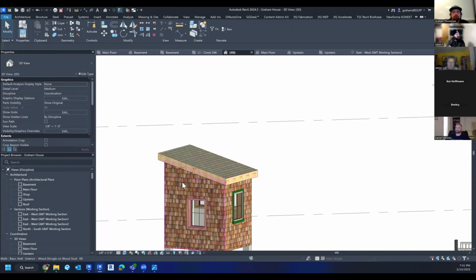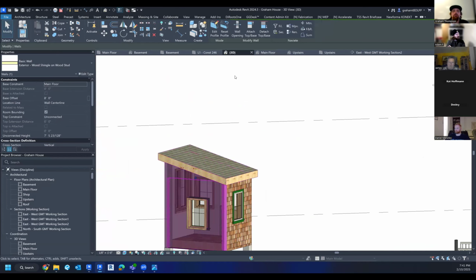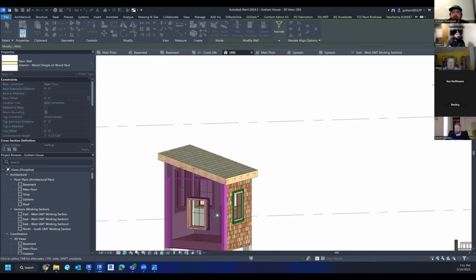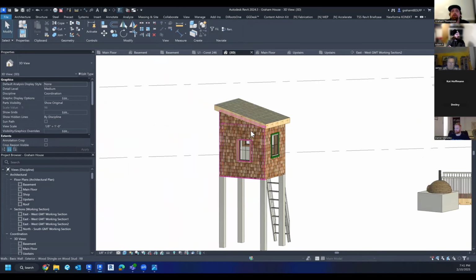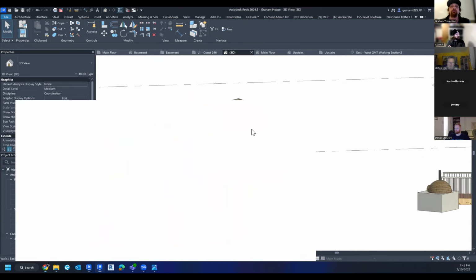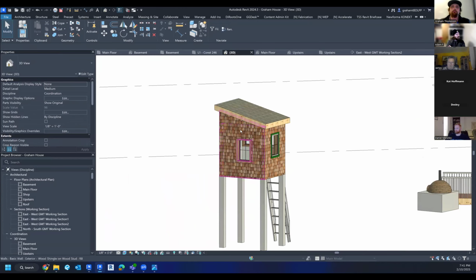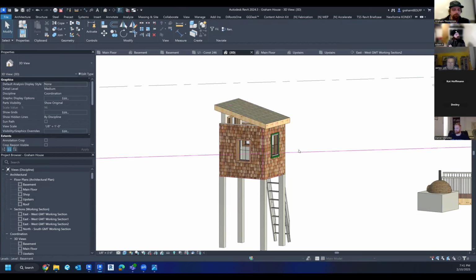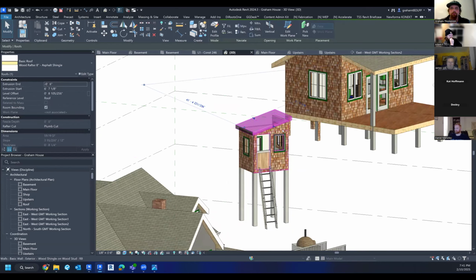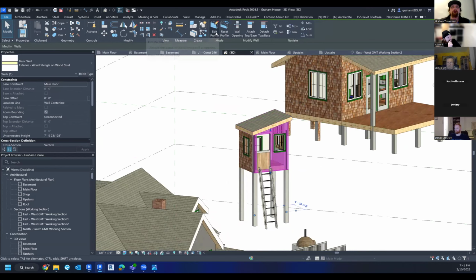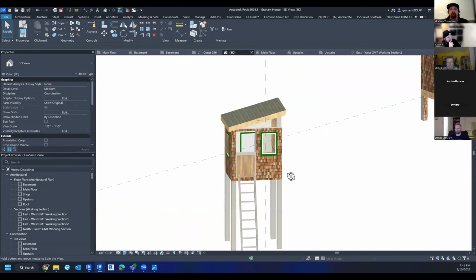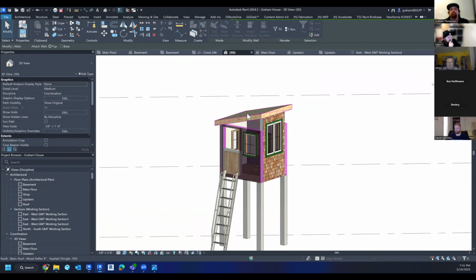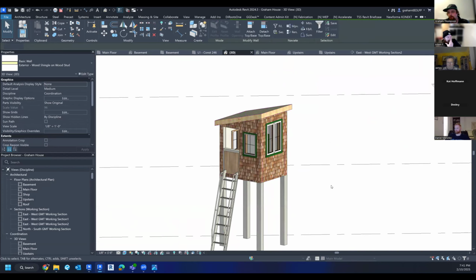Last but not least, I just want to make sure that all of this works. So I'm just going to attach the top and base, unjoin elements. Now, for some reason, I think when I drew this, I actually drew it as a profile. And I've learned some stuff since then. So let's reset profile. And I'm going to reset all of these profiles. And now I think if I just use attach top and base, there we go. And now it attaches them.